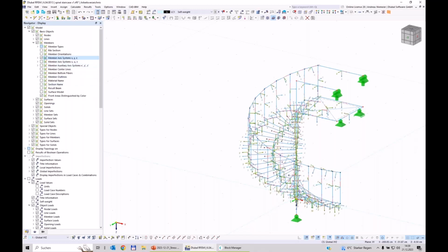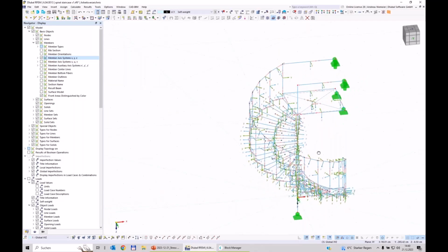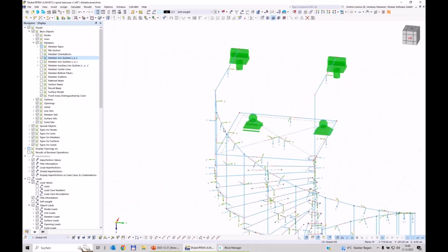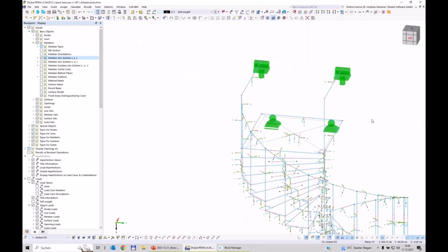Let's say I know the handrail coordinate system I aligned in the stair step already. The only point missing is that all is showing to the inner side, so this will be rotated also to the inner side by 180 degrees.